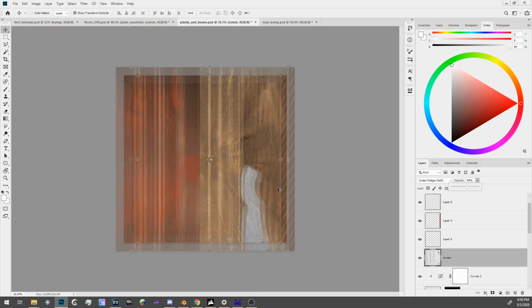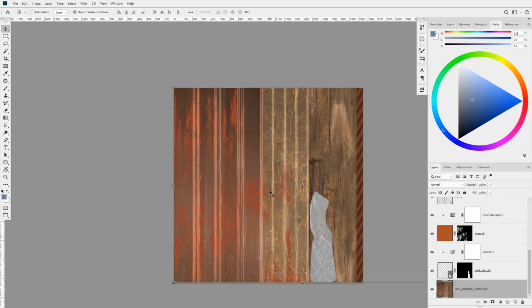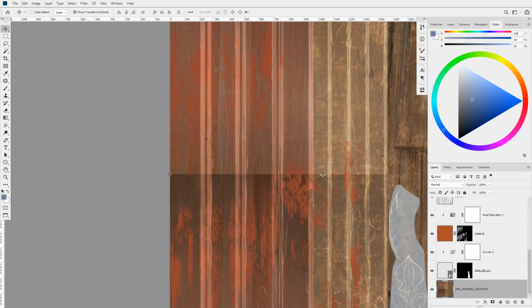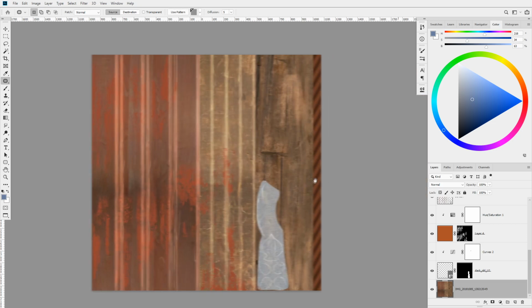Now let's make sure that the diffuse map is tileable. Merge the bottom texture layers and offset them by 50%. There is an ugly seam in the middle now, which can be removed using the patch tool. When finished, offset the texture back.